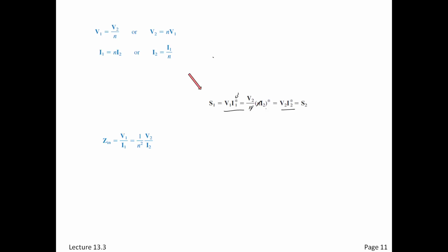All right, what about the impedance? It's V1 over I1, right? And that is simply taking the first two, making the product of these two, written like that. And the second two are the product there. So this same cancellation thing is going to go on up here, right? To give us this, we've got the N over N, so it's going to be V2 over N I2, so 1 over N squared.